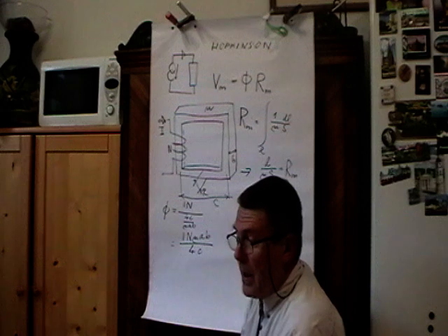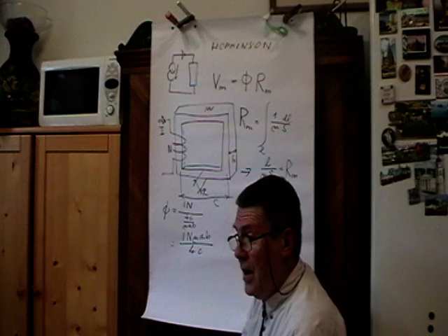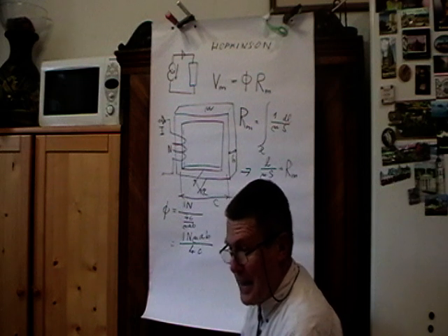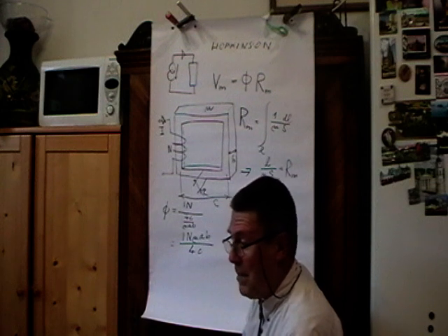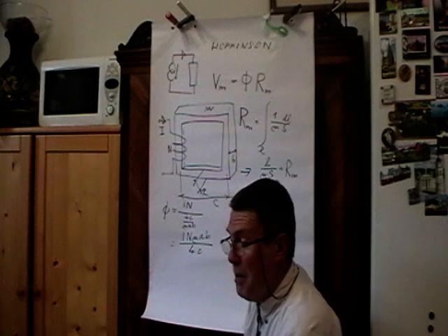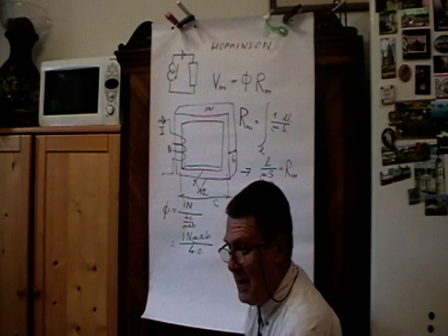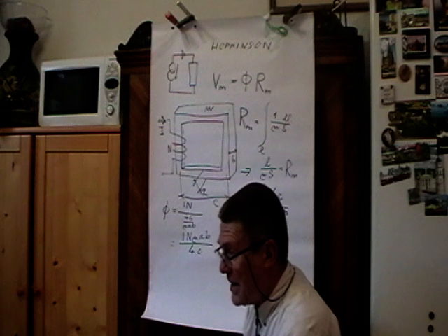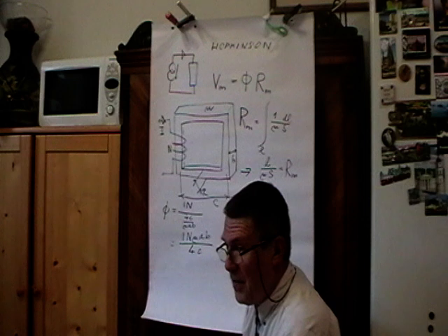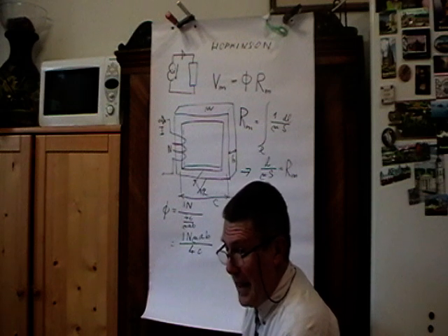But a short remark at this point. For many applications it would be the best way to have as high magnetic flux in the core as possible, or as high magnetic flux density. Unfortunately, most of the materials we can produce, or all the materials, have nonlinear behavior, and at some flux density they stop to behave as magnetics.